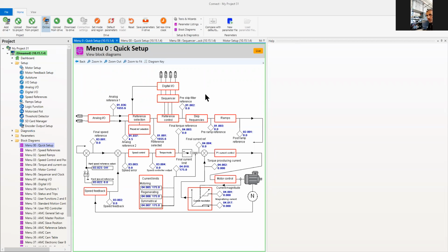Yeah, that slip factor must be applied because the actual RPM cannot be 1,800. It's supposed to be less than 1,800. The synchronous speed is 1,800. That's right. Okay, so I'm assuming you previously calculated the slippage and then subtracted it from the RPMs. Yep. So slippage would account for 75, if I'm not mistaken. That's right. Okay, cool. Thank you.